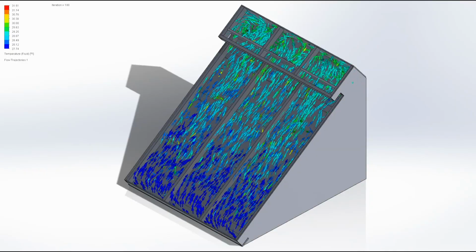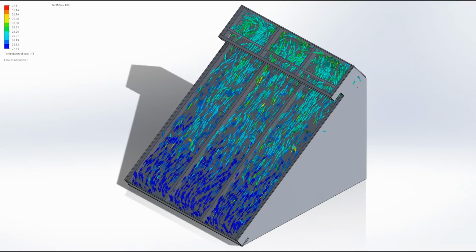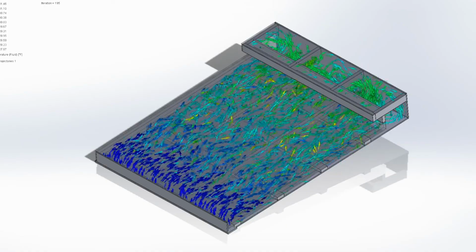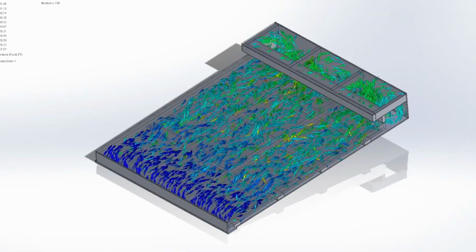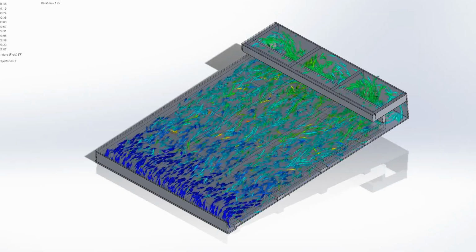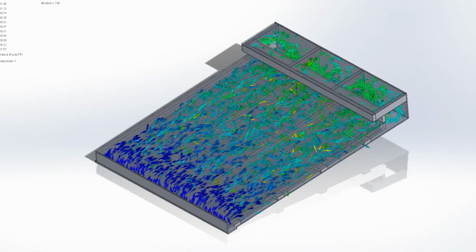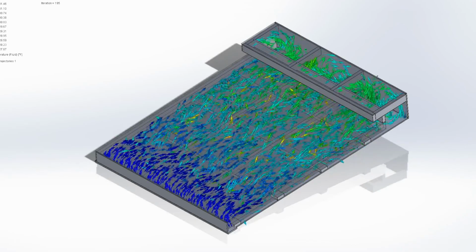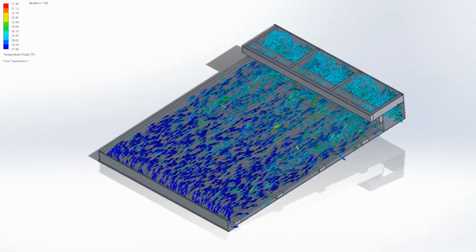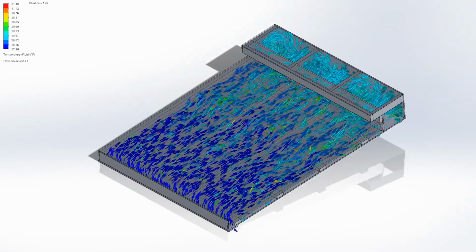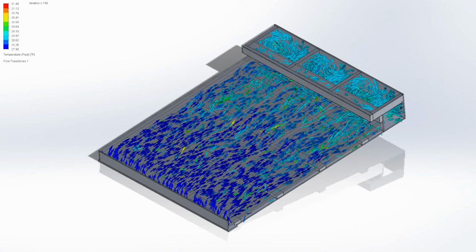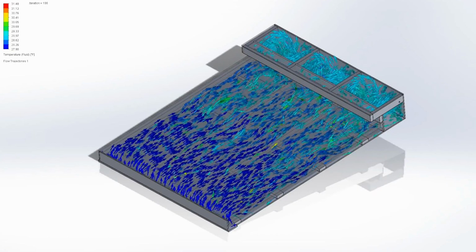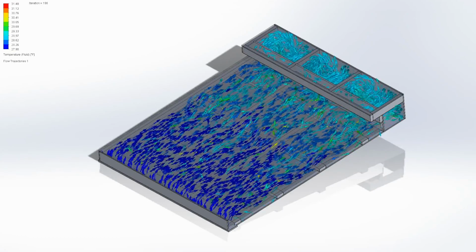The existing cold roof system that our sponsor in Big Sky has is a pitched roof using natural convection. This flat roof has a slope of 1/12. As you can see, the air heats up more quickly since the flat roof has a smaller CFM due to the forces of natural convection. The next roof has a fan added with a fixed CFM of 93 to improve the performance of this roof. The 93 was a part of a previous calculation for a 50-foot long roof to keep the exterior below 32 degrees Fahrenheit.